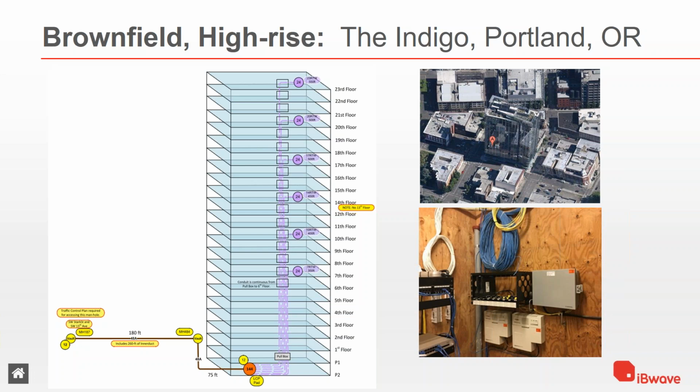It is a relatively newer building, so it had Cat5e runs coming back from each unit to the IDF closet. You can see in the bottom right a picture of that IDF closet. Relatively clean, abundant backboard space. There's access to power the ONTs in this location. And because we had the Cat5e drops, it made sense to load ONTs into the closet location and take advantage of a quarter of the fiber required by using the multi-porting functionality of the ONT to serve up to 4 units each.